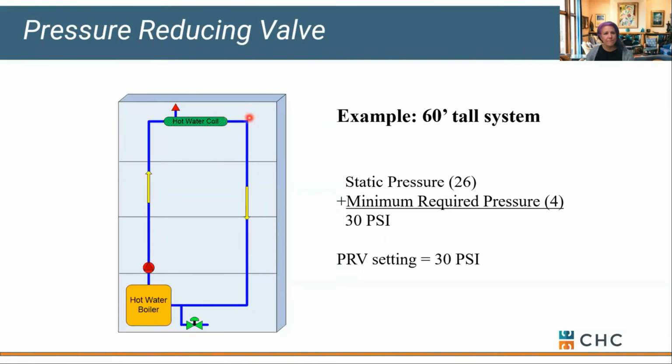So if we're maintaining 5 pounds, I'm going to call this a penthouse or upper floor, 5th floor, if you will, and we've got 30 in the basement, that might affect our expansion tank and the fact that our pressure up in the penthouse might fluctuate from 5 to, I'm going to say 20 or higher. In the basement, it might fluctuate from 30 to 50. Really depends on what the relief valve would be of our boiler or our equipment, depending on where it's located.